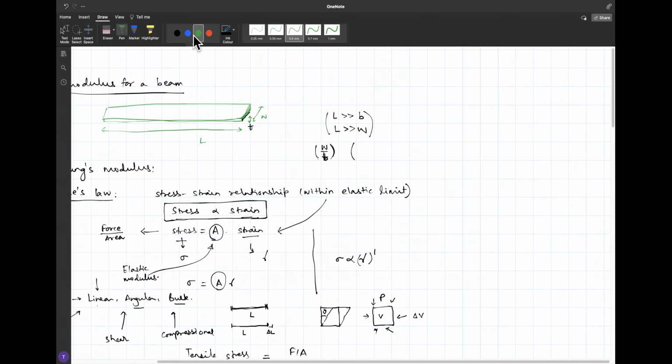The reason I suggest you do this is because if you now plot, you will get a straight line, right? And if, let's say, I plot stress, I mean, this is not what you're plotting, but this is what I told you, right? Hooke's law, that it's linear, which means if you measure the slope at any point, that will give you the Young's modulus, right? Change in this divided by change in this. That's how you measure the Young's modulus, and it's the same because the response is linear.